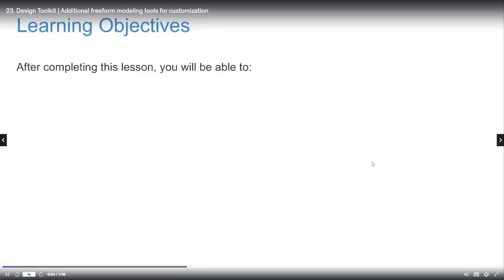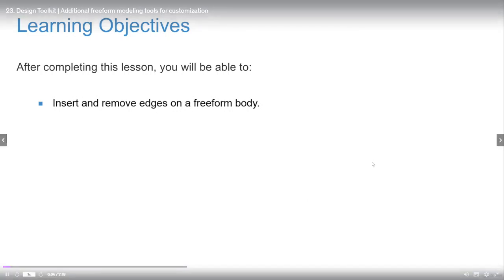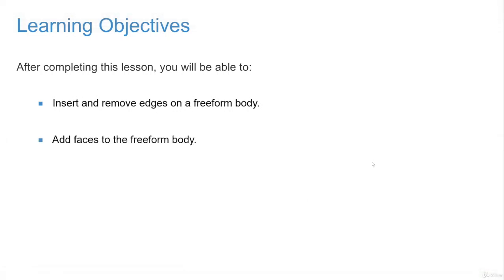After completing this lesson, you'll be able to insert and remove edges from a freeform body, add faces to the freeform body, and control the display of the model for editing.